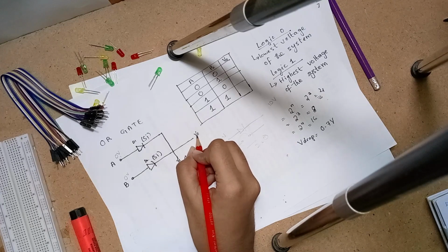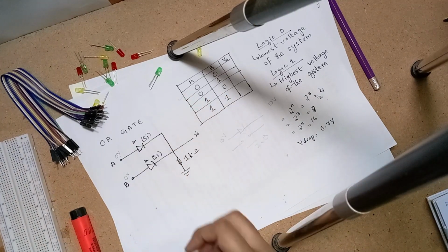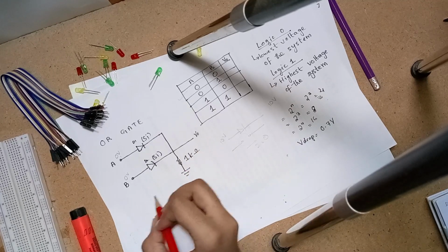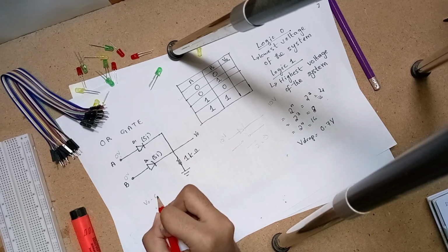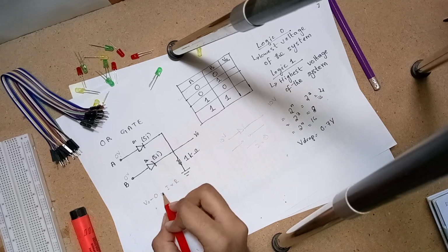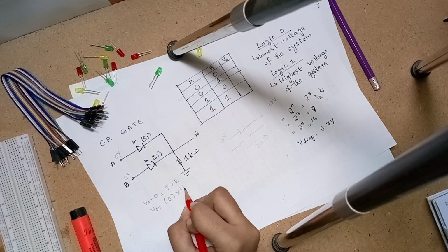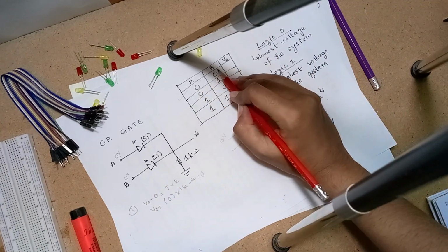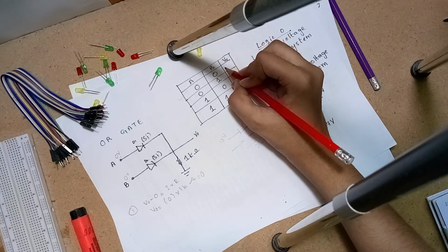So now we are going to find V0, the output voltage, in the first case. If you use your common sense, the output voltage would also be 0. But let's use Ohm's law, which says V naught minus 0 equals I into R. In the first case, the current is 0, multiplied by 1 kilo ohm, and the answer would be 0. So this is the first case when both of the diodes are turned off, or both of them are at logic 0, the lowest voltage of the system. So it would simply be 0 again.